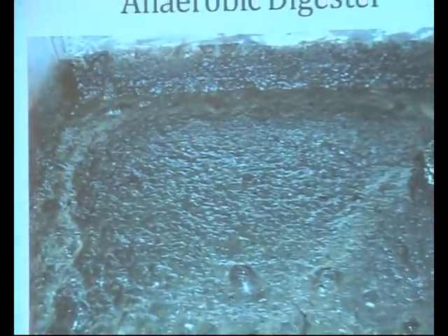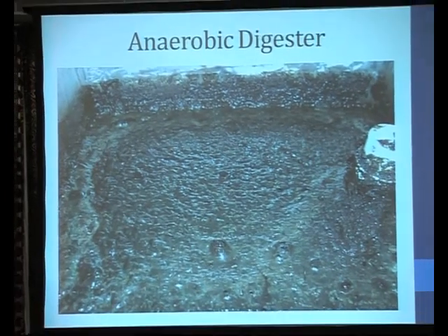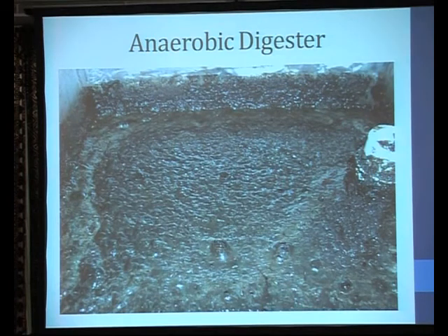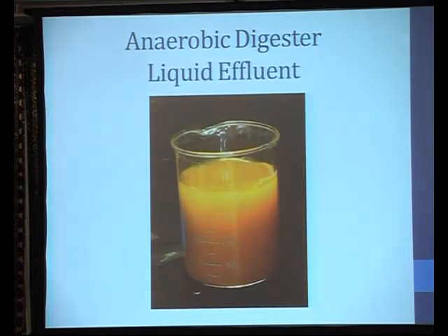Here's another picture. You can see the tube where we're feeding it. This is before it's being filled. You can also see we have an aquarium heater here, and you can see the overflow. And that's a picture of the surface of the sludge. You can see some scum. You can observe some little bubbles of biogas pumping the surface. That's during operation. To the right-hand side is the overflow.